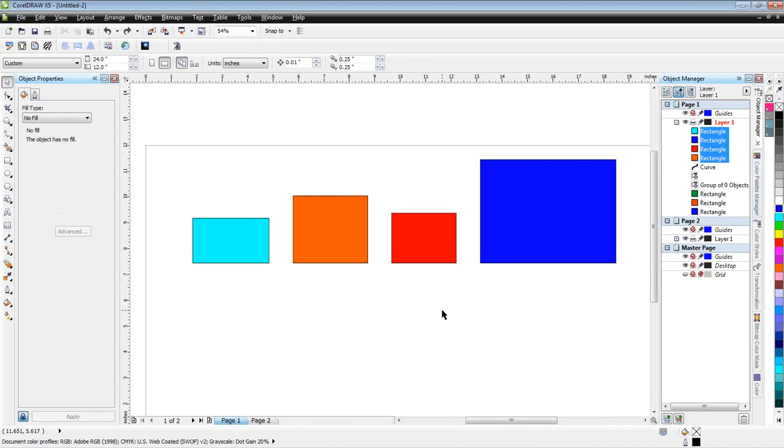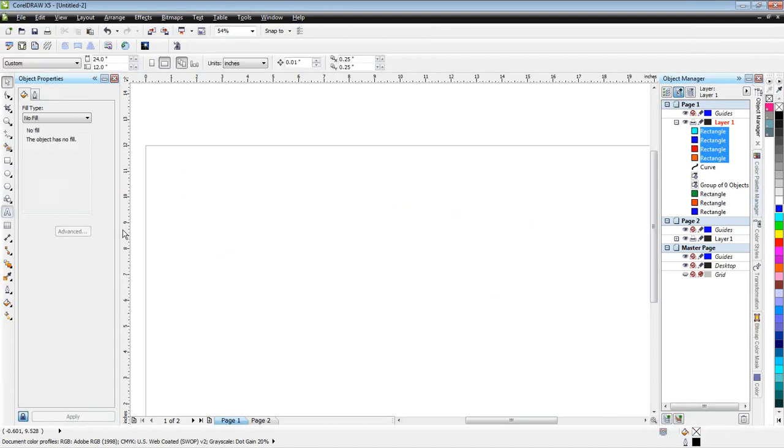If I need to change the properties of the individual objects later on while I'm working with it, I'll want to use the group function. And that way I can move them around and keep them aligned and keep them locked together. It's kind of like screwing them all together so that they stay in one piece, but they have individual properties, whereas the combine is kind of like welding, and it makes it all into one object with all the same properties. So let's take a look next at working with some text.